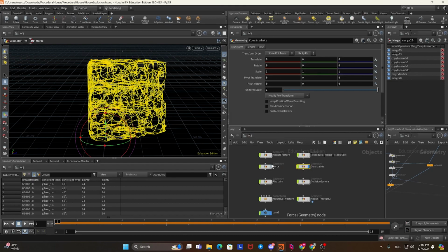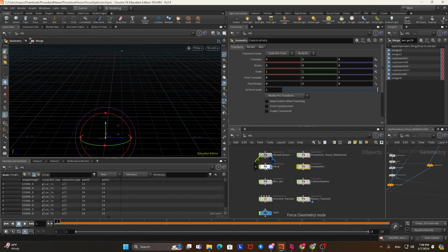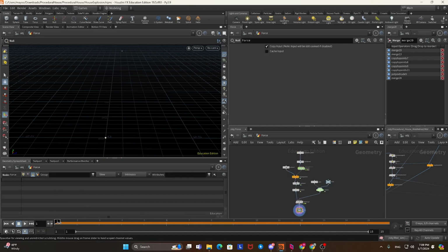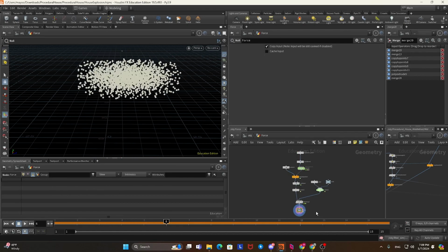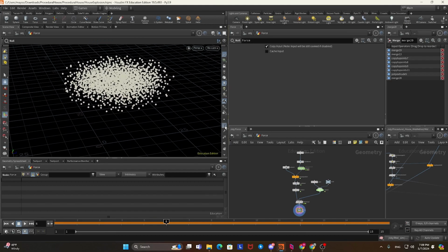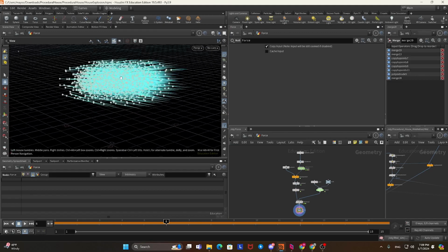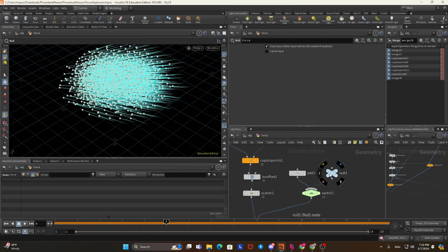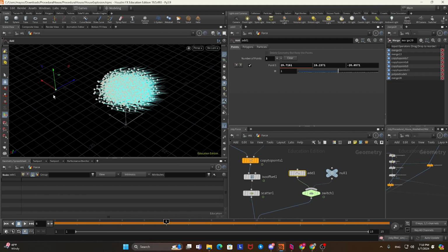After the constraint network, I made a force. The force activates on, I think, frame 6. It's just a huge point cloud that has the force generated, and I can move the force origin. You see, there's a point over here. If I move it, it's going to move the force to a different direction, and I can control its amplitude by scaling the vectors up.